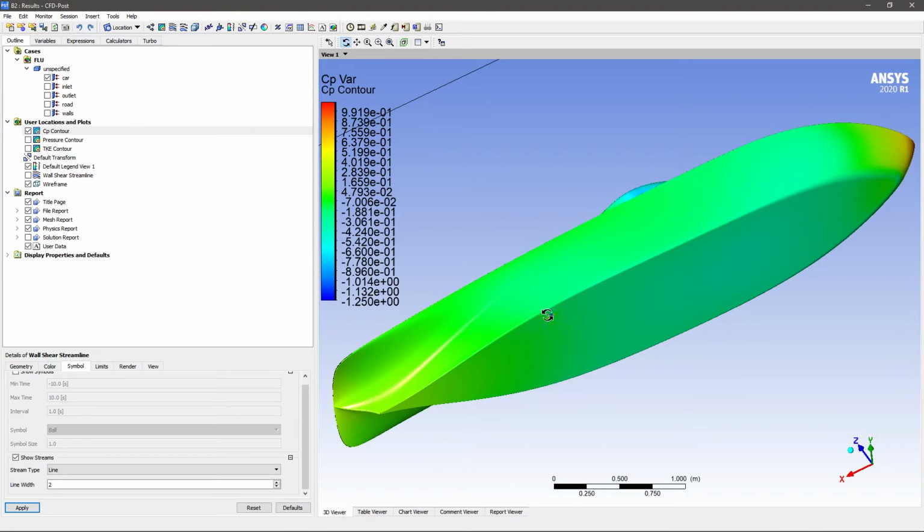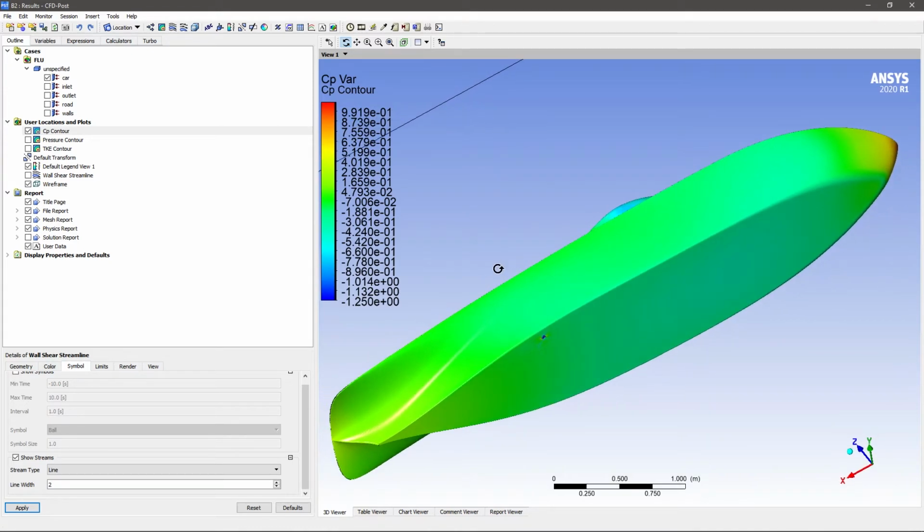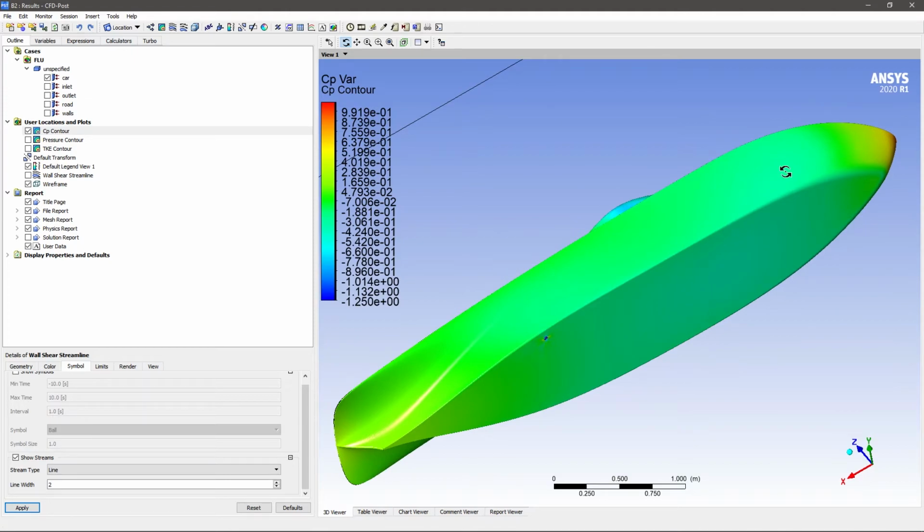You might notice that there's a little bit of an anomaly down here that might indicate an error in meshing or an error in the sim. So it might be best to consult with some expert advice to verify whether the results for your sim are accurate in that case. In this case, the job here is just to get the post-processing done, so we will alert anyone of any anomalies like that. Make sure to keep your eye out when doing this kind of task.